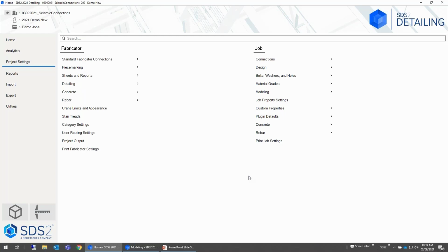No, that covers it. The thing I would add is you saw on that BFP slide that A36 is allowed for flange plates, but due to some of the limitations they have on the length of the bolt group on the flange, it appears that really the A572 Grade 50 is the way you need to go in order to get a connection. Okay.